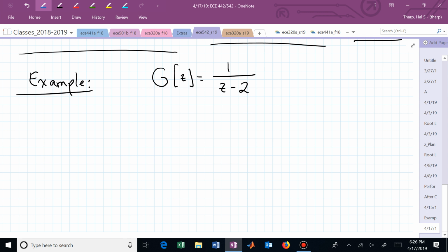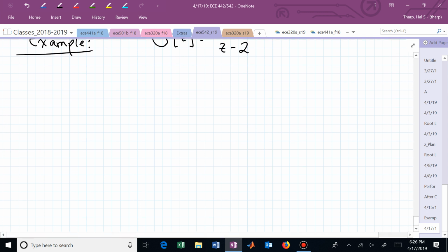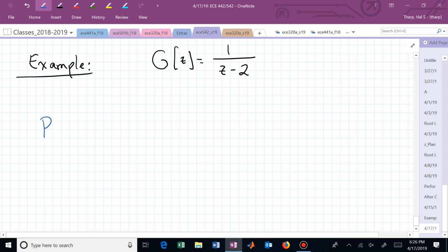PI. You say, I need to put an integrator in here, and I can do that with a PI. So now we say, okay, we have a PI controller, we have a C of Z, and that has the structure, and now I'm just going to really confuse you. I'm going to say the 0 is at beta instead of alpha.